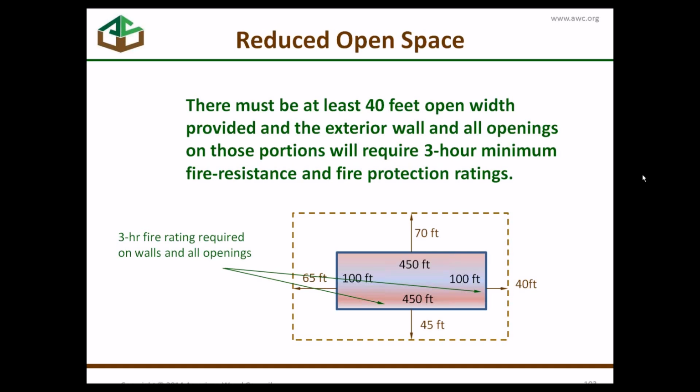There's no requirement, and you would go all the way across the street for your W measurement, to the center line for your fire separation distance measurement, but there's no requirement that that street has to be any particular width. There may be setback requirements for the street itself. That's not really regulated by the building code. But in terms of the building and the exterior wall rating, you can always use that street no matter how narrow it is for open frontage if you have the width.